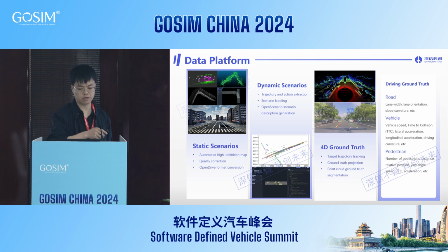So you need to trigger or select your data based on a few rules or based on the data collected by these sensors. For example, you want to collect data when the driver has intervened, the vehicle cannot perform as suggested, or there's a large acceleration or deceleration of the car, or when passing a very complicated intersection where the test driver pushed a button to record that this is a hard event. Based on these flags, you can do a lot of filtering and selection to find the meaningful, high-value scenarios.